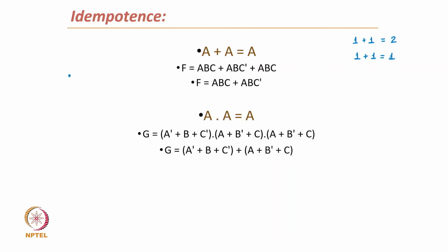For example, we have a single node and we want to measure how much is the output, and there are two gates which are writing output on this node. So, gate number 1 is producing 1 volt and gate number 2 is also producing 1 volt. So, here the output, which is kind of a wired OR output, is not 2 volt, it is still 1 volt, because 1 volt will come from here and 1 volt will come from here.